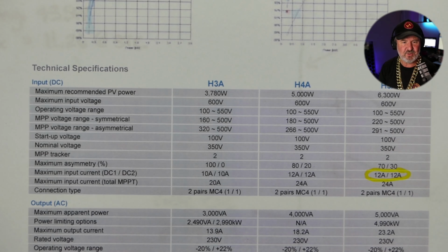Now, this is where it gets tricky, because it sounds like it's a maximum, but it's a maximum of current that the inverter can convert. It's not a maximum of current that the inverter can pass through under fault conditions. So you actually need the short circuit current rating of the inverter to find out will these panels be suitable for this particular PCE. And it's nowhere to be found on the stock data sheet.